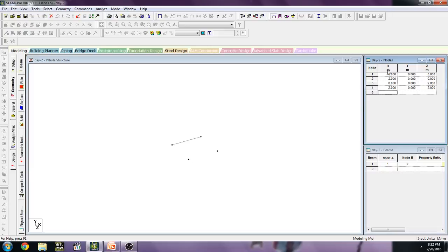So this is only x and y as distance. Because of this particular coordinate system, you can create any kind of node just by putting their values over here. If you measure the distance between those 2 nodes that I have made, it is 2 meters. I will show you later. Okay, but first of all we want to create a plate over here. So let's create a plate.